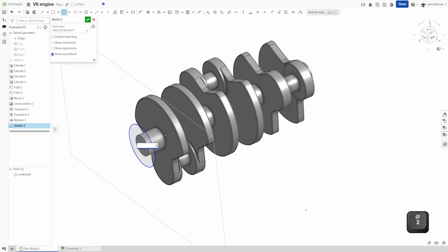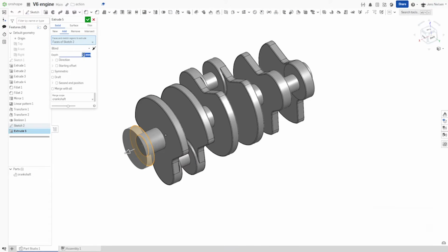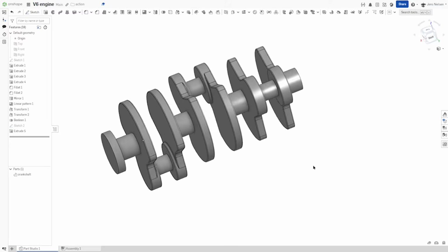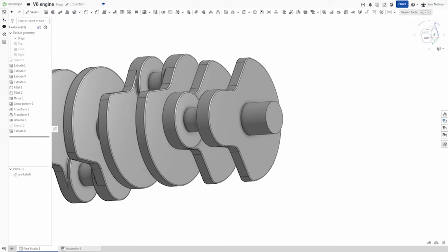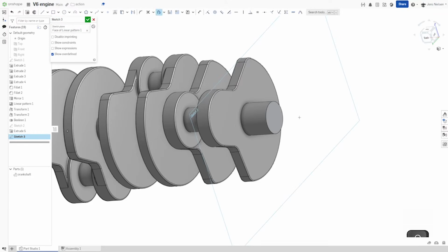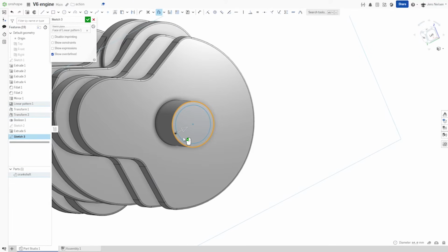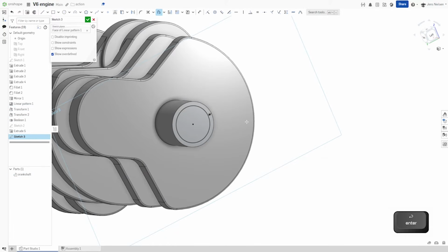The circle 122 and extrude that with 22 millimeters, adding to our part. And on this face, I'll make a sketch offsetting that circle to the inside with 6 millimeters, and repeat that one more time with that same value.